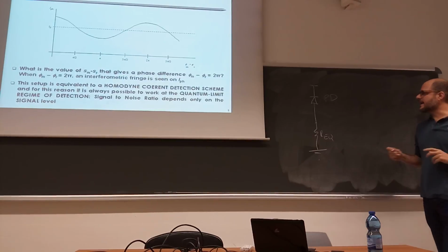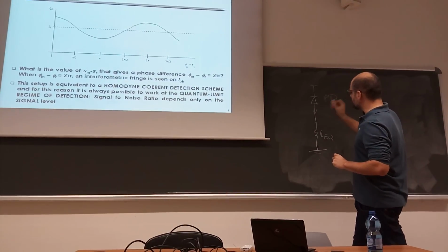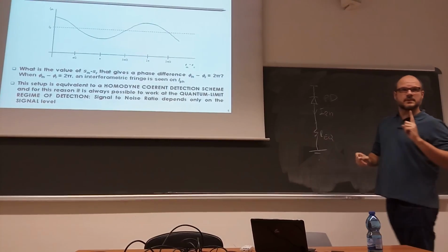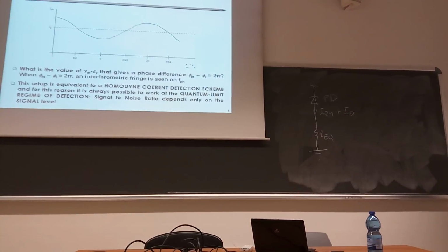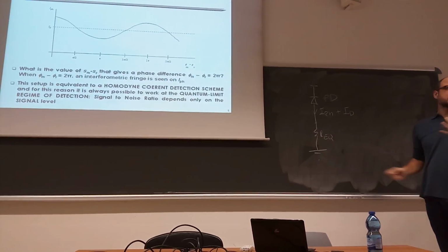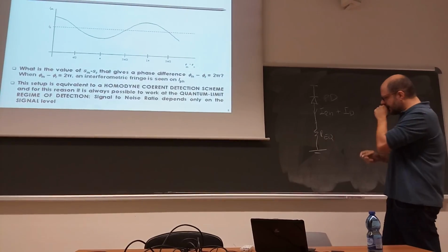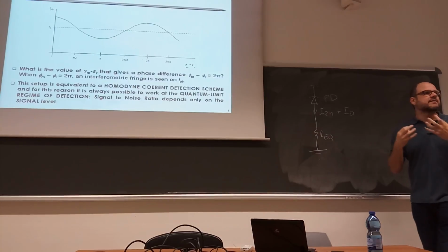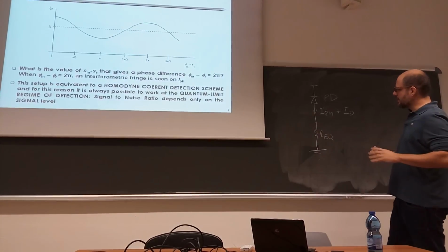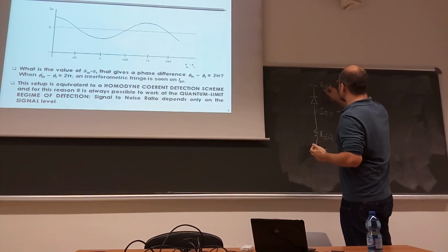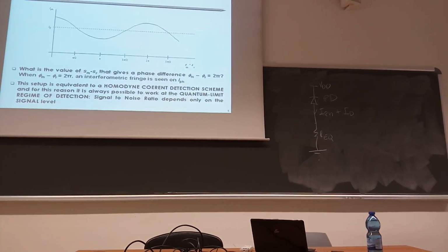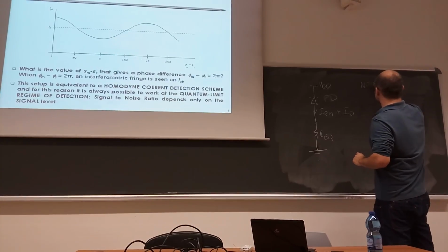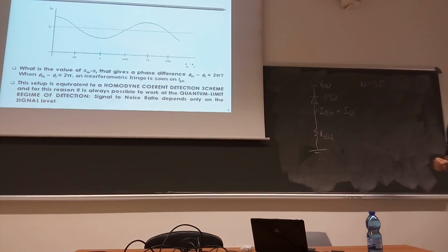So what do you have? You have two contributions of current: the photodetected current, but you have also the dark current of the device. For each photodetector that you use, you have a current even if you don't have light, and this is called the dark current. And this is, as I said before, the input resistance or the equivalent resistance of your circuit. This can be a power supply value that is higher than 0, nothing more. Now if you look at the noise of this system, you have three contributions.